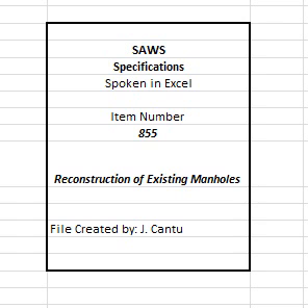7. The test head shall be inflated in accordance with the manufacturer's recommendations. 8. A vacuum of 10 inches of mercury shall be drawn, and the vacuum pump will be turned off. 9. With the valve closed, the level vacuum shall be read after the required test time. 10. If the drop in the level is less than 1 inch of mercury, final vacuum greater than 9 inches of mercury, the manhole will have passed the vacuum test. 11. The required test time is 2 minutes.